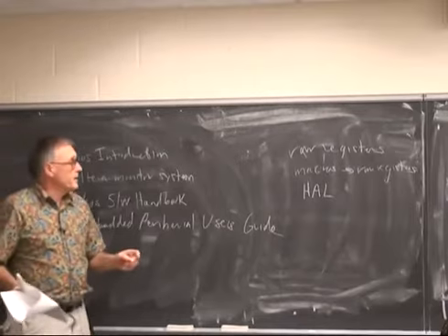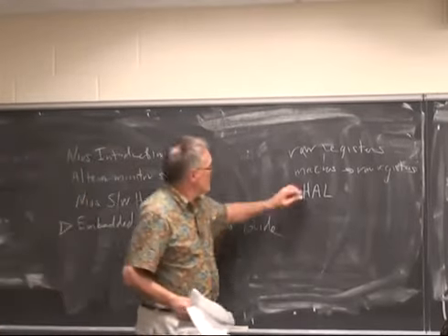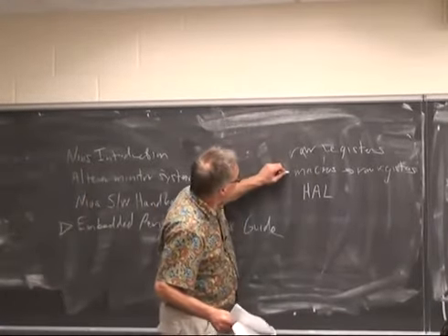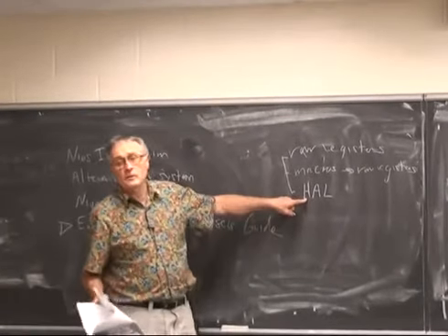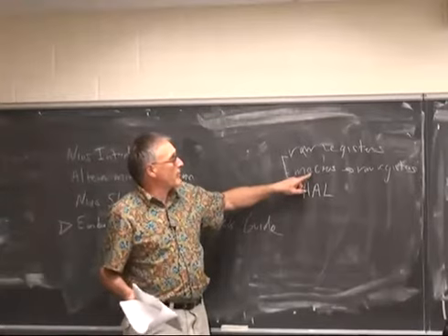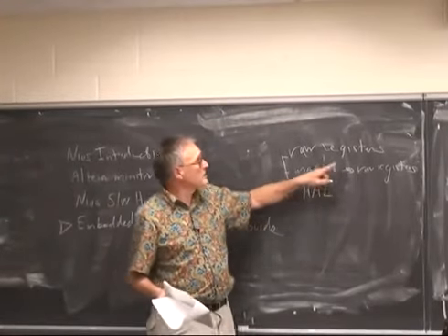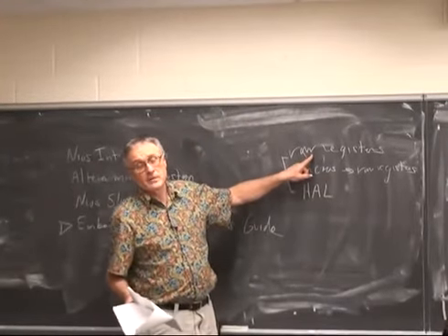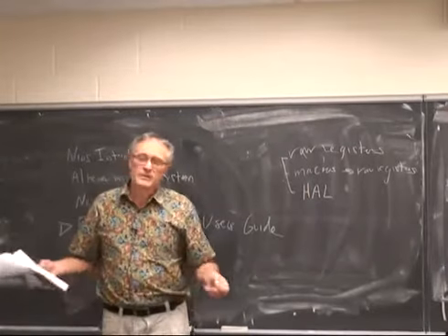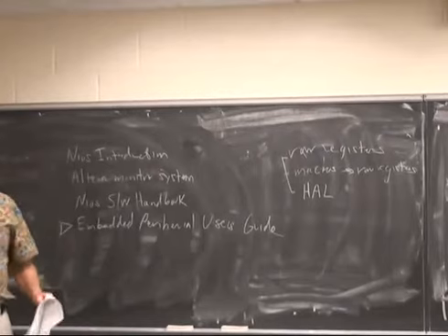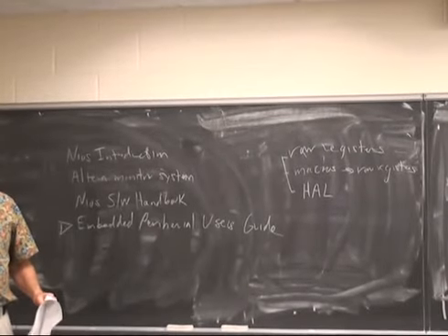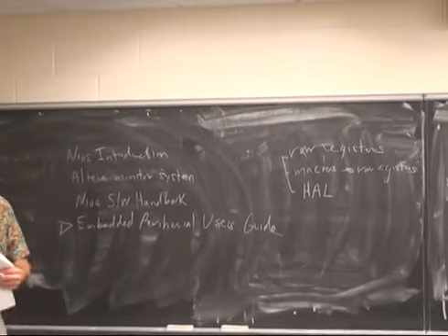And what I usually end up doing is some combination of all of these. I use the HAL for some functions, and macro to raw registers for some functions, and just bit blast other registers for other functions. And I'm not sure why, except it seemed to be the order in which I learned things. So you're not required to do it in any particular way. Whatever style works for you works.